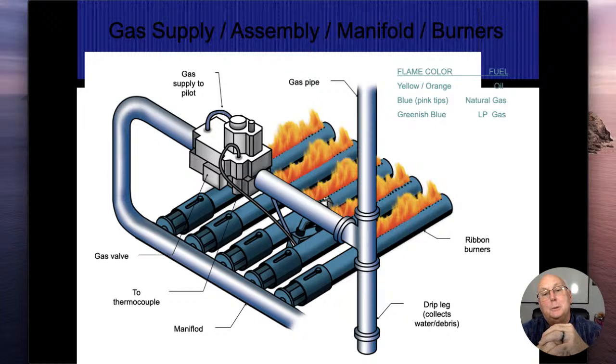Those sliding tubes and the opening as I'm coming off the manifold, those are where I draw in my combustion air. It's called Venturi tubes. As the high pressure gas shoots in there, that creates a negative pressure around it, and draws in fresh air and oxygen.